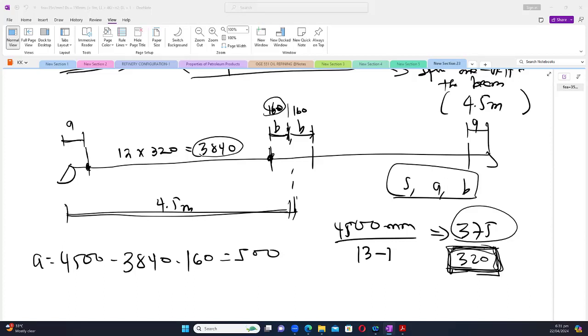And then the one below the concrete, which is the steel. And we say that these two materials, which one will slip first? Which one will slip first translates to which one is minimum. That one will govern the whole slip action. But if we put it at the neutral axis when we're designing for the moment, it could be inside the steel. And there's no slip inside that steel section. That part cannot slip.